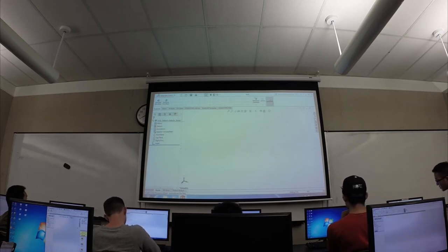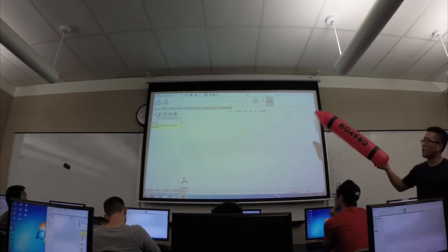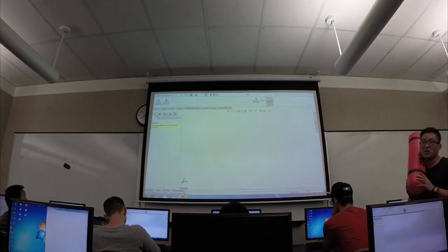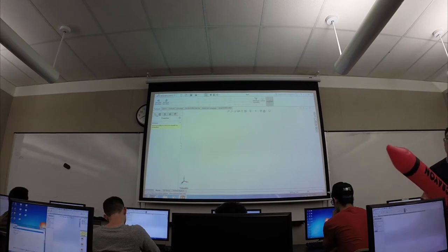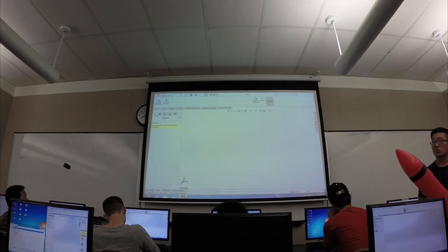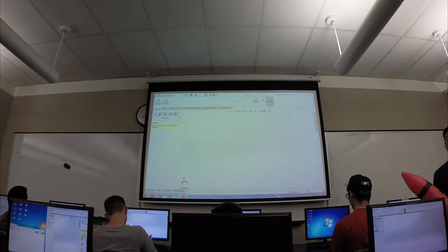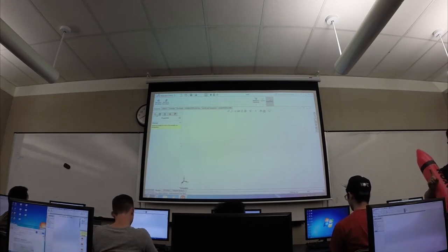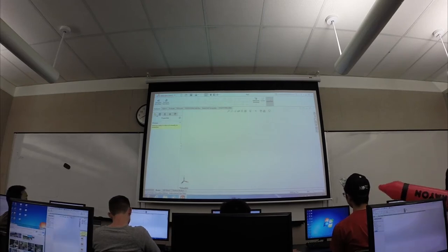Cool. Also, the next tab in the tool pane is properties. You'll see more of it in a bit once we start sketching things actually. It defines the parameters of your sketches or your parts. So you could define length, angle, how it's constrained to another sketch. So if you have two lines, right? If you want them to connect at one end, you could define that in the properties tab as well.